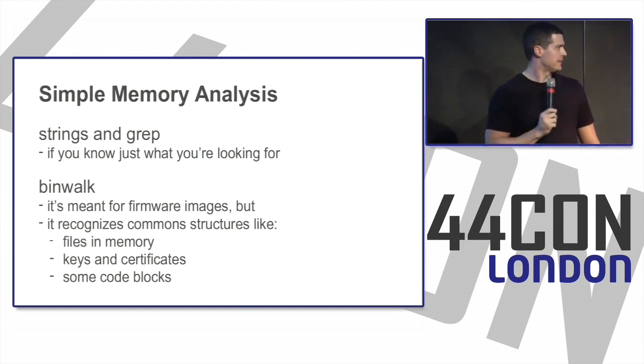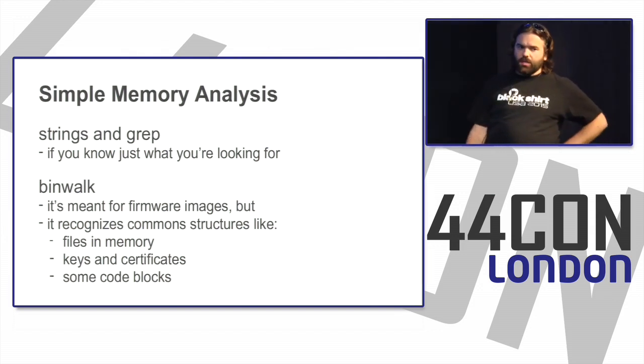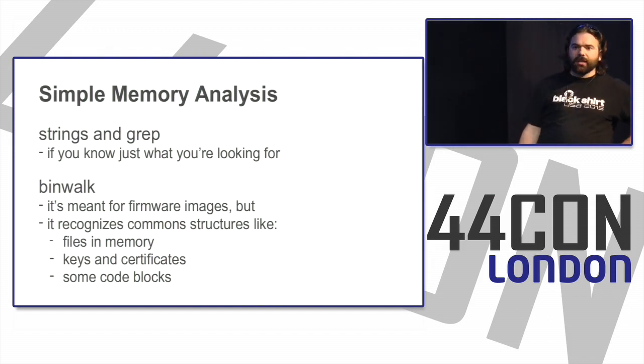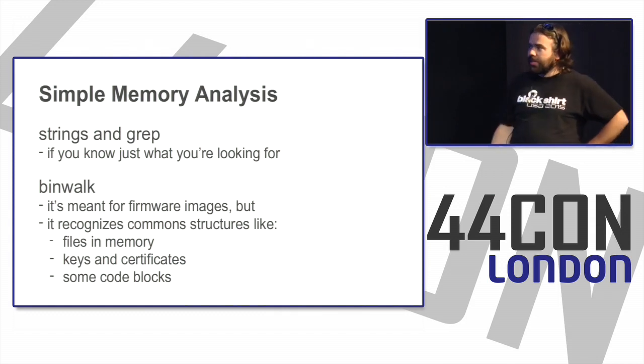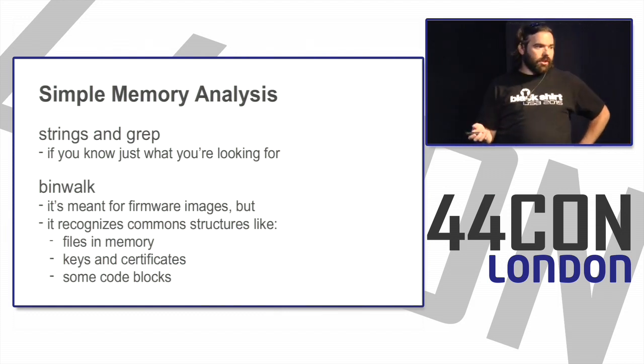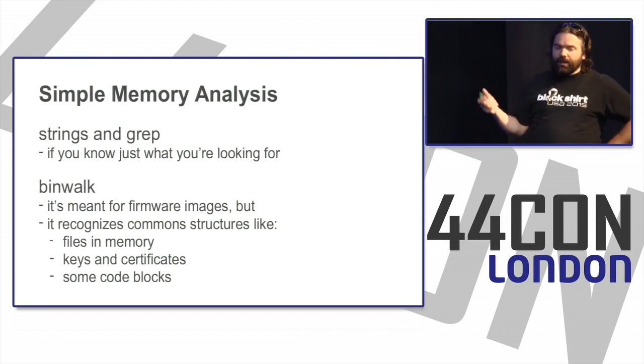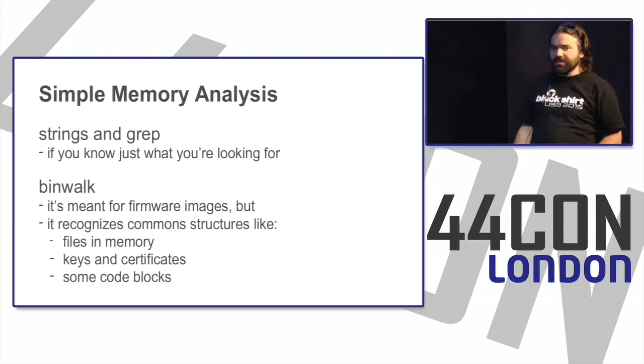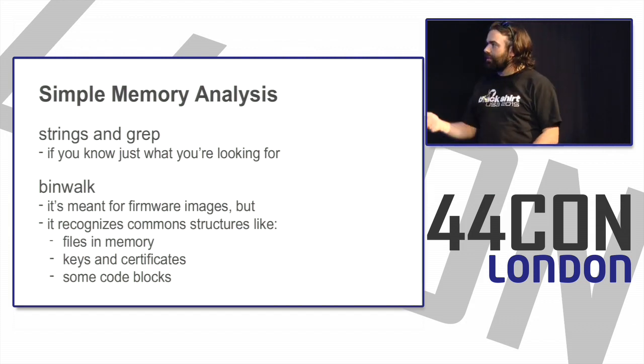Also, Binwalk is really designed to be a file and firmware image analysis tool, but because it knows the shape and structures and all the magic words for a huge number of file formats, it's really good at finding all these files that are located in memory too. And it's great because it's just one command, binwalk and the file name, and you get a list of what it thinks it finds inside this file.